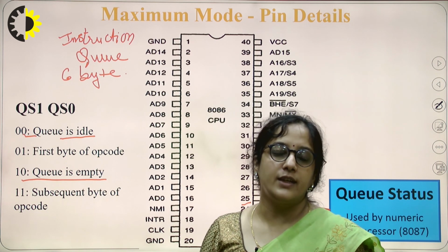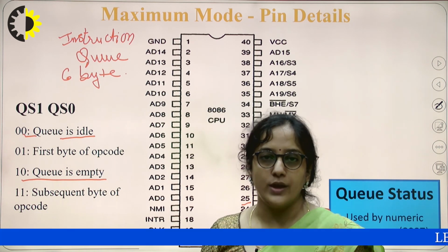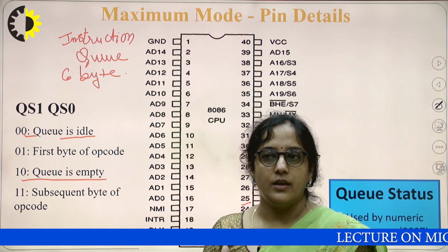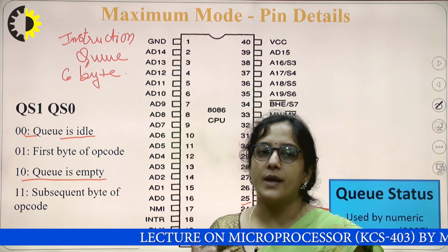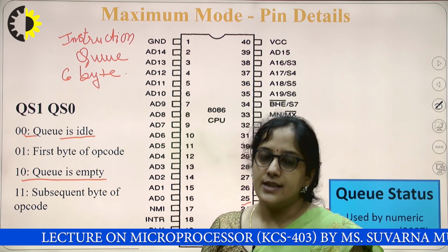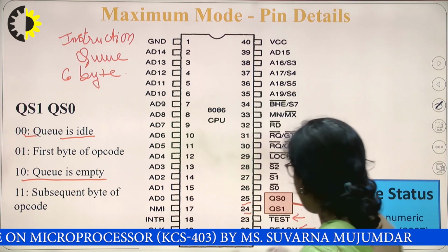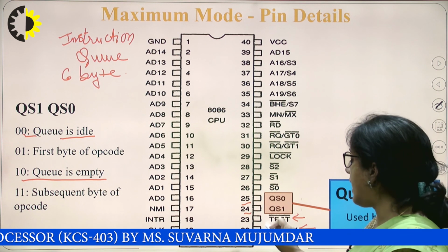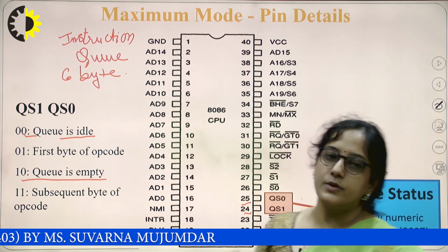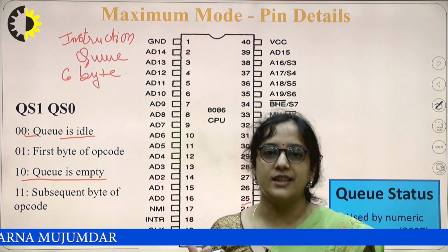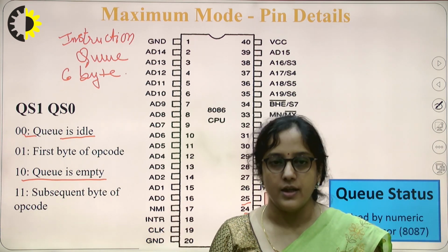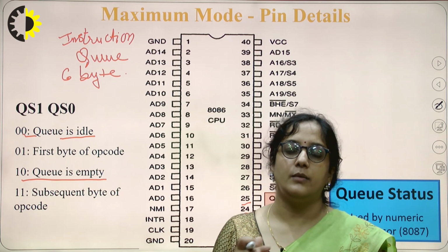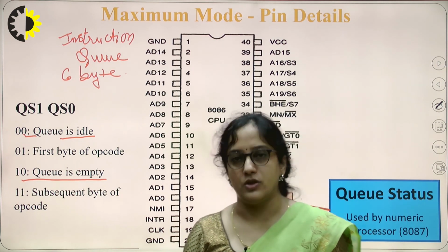If some peripheral devices connected with the 8086 are working at a slow frequency and cannot keep up with the 8086, then those peripheral devices make this pin high, indicating that the microprocessor has to add some wait states in the read or write cycle of that peripheral device, so that both devices can cope with each other.